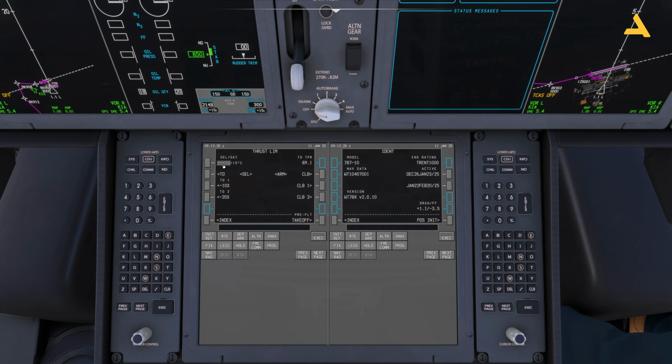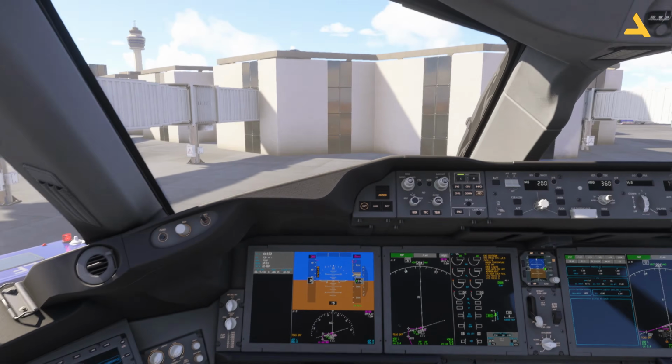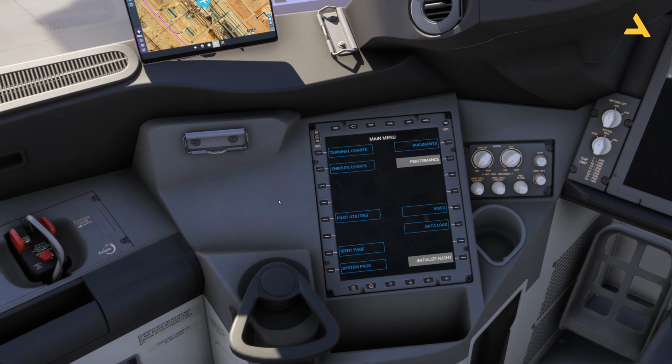Plus, you also enter an assumed temperature here, which tells the flight management guidance system that it's really hot outside, so the thrust is further reduced. And for the climb also, you can reduce the thrust by different settings. Let's say you can keep it at over here. So I keep everything over here, and then I let the takeoff performance calculator do all the things. So just go to this page, and now I will go to this tab to do the performance.